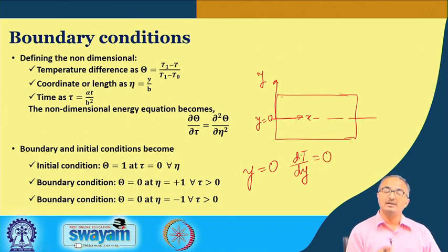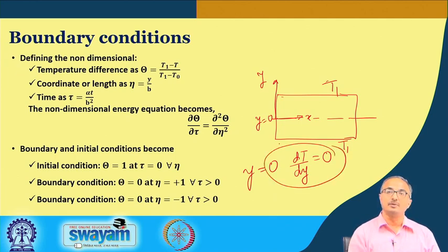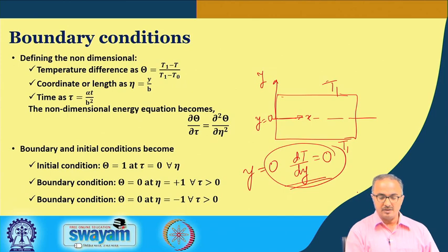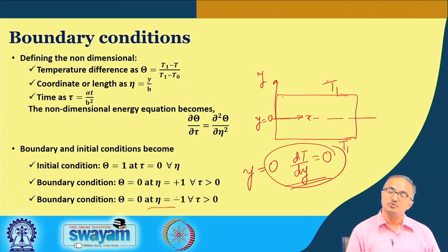So, you can see that depending on the geometry we are considering, my boundary condition would change. For the problem on both the sides I have T1, T1, it is becoming the Dirichlet condition. But if I consider only 1/2 of this, we find that on one side we shall be having the Neumann boundary condition, and this boundary condition is telling about the symmetry effect. So, that is how it is coming. You can choose either this formulation or this formulation, it does not matter whichever you choose, you will obtain the same result.